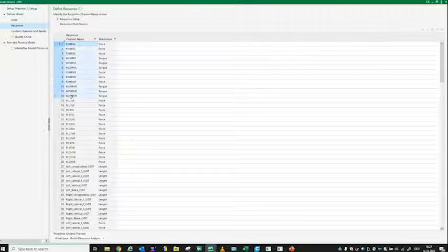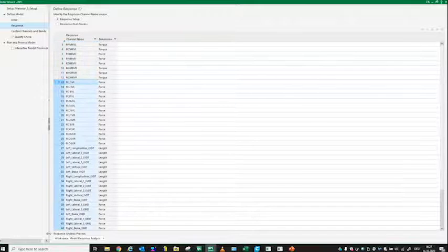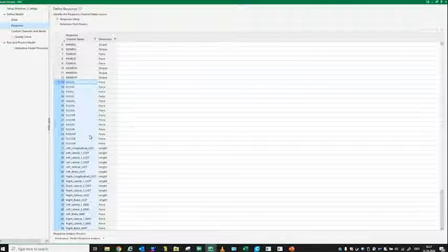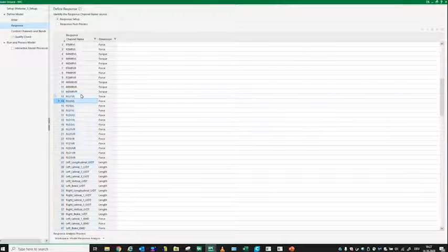So here, these are my wheel force transducers, Fx, Fy, Fz, and then the corresponding moments. For 2 corners, of course, you have these channels twice, or on the other side twice, more or less. And then these are parts and rig things which I'm not interested in because they should not be part of the inverse and I'm not using them. I just want to monitor them or just kick them out.